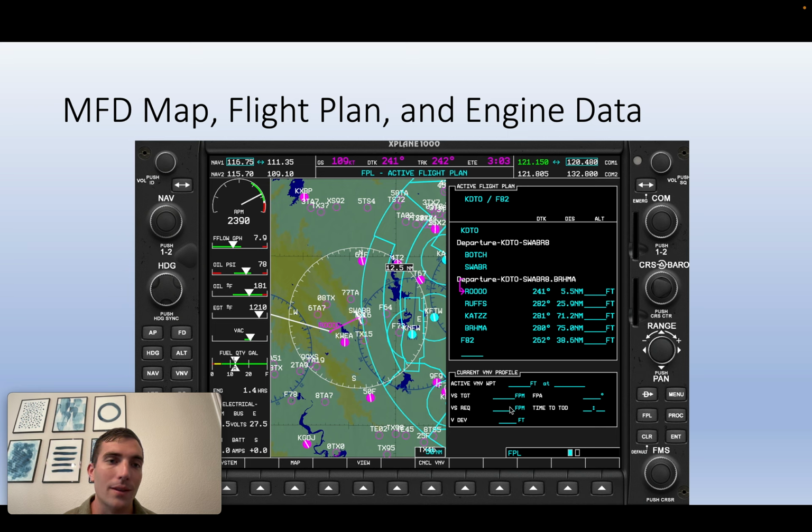One thing that the G1000 displays that I don't have in my steam gauge carbureted Cessna is that I've got the RPM, the oil pressure and oil temperature in my airplane. However, I don't have fuel flow, I don't have EGT, and I don't have precise engine fuel tank indicators. They bounce around. They're not very reliable. I've heard people say the only two times they're reliable is when they're reading full or when they're reading empty.